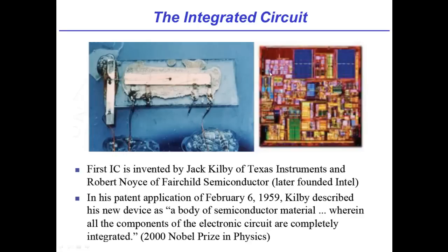that are wired together. Now, this was not done by independently gluing in 600 million things and then automatically wiring them together. That would be incredibly error-prone, and moreover, you would have a lot of error even in the component values. The beauty of these chemical processes and this concept that Kilby and Noyce came up with is that we can build them all at once, and in the end, you have this integrated chip. This is why your processors cost as little as they do. And I should also point out that cost is another big benefit of this. You can build 100 million or 500 million transistors on that single chip for just a little bit more than it costs to buy a discrete.